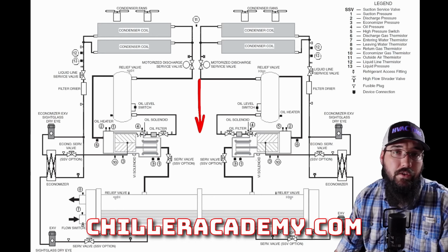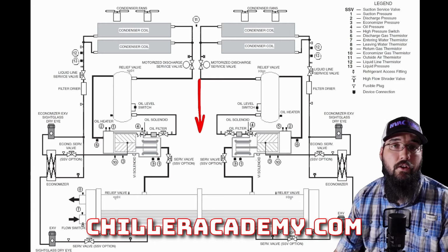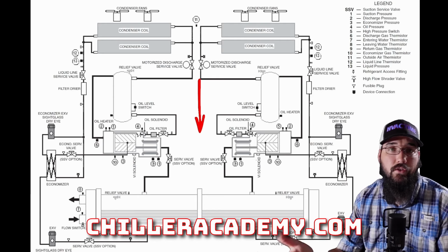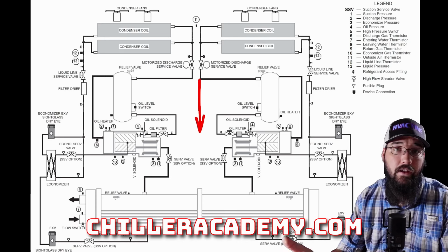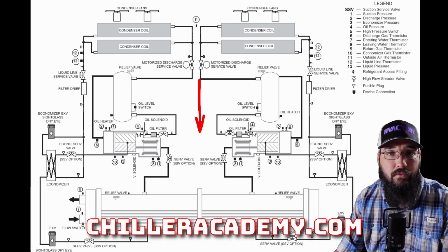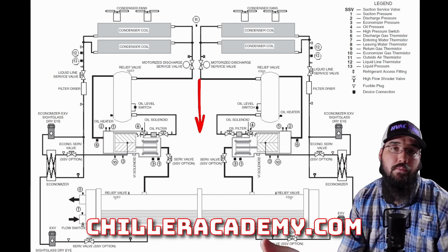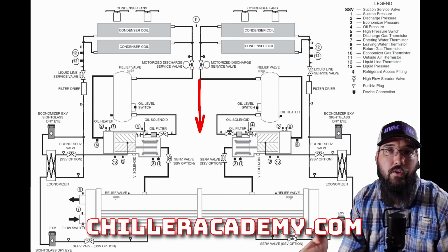Daikin does something similar to what Trane does, where the lead that's already on is going to stay loaded. It's going to start the lag, and it's going to let it start to ramp up as the lead will start to ramp down, and they'll eventually kind of level out somewhere in the middle. You just be mindful that depending on the brand, you could have a different control sequence.